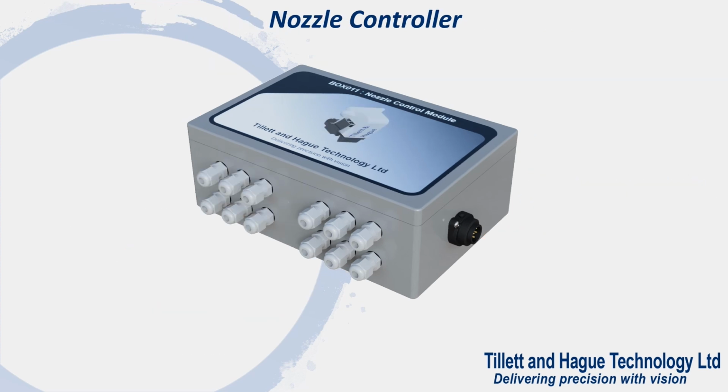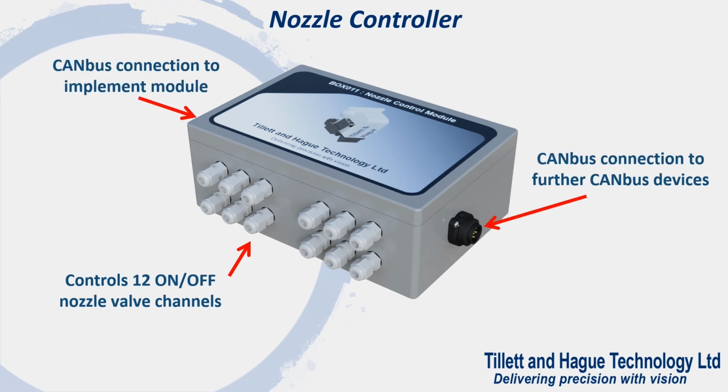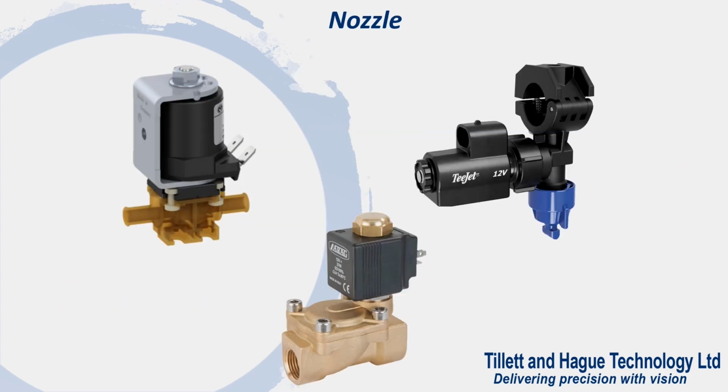This is a 12-channel nozzle controller, which can be used to activate up to 12 nozzle solenoid valves with a maximum nominal current draw of 1 amp per channel as standard, though higher currents are possible on request. Again, these controllers can be linked to provide more output channels. Our nozzle controller will drive any appropriately sized solenoid valve operated nozzle, including latching valves, but for many of our precision applications we found that the existing commercially available nozzles were not appropriate.